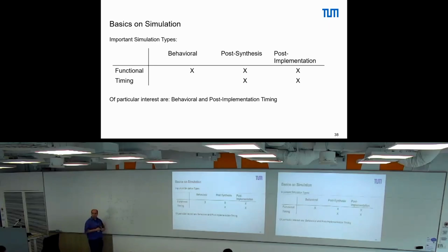Usually, without giving now precise numbers, because we'll do some computations like this in the exercise, an OR gate is slower than an AND gate, and if we have here an inverter, then we have here an additional gate. So the most critical path is most likely, including clock to Q, the one which goes here, right? That's most likely the most critical path. We call it TD max, right?